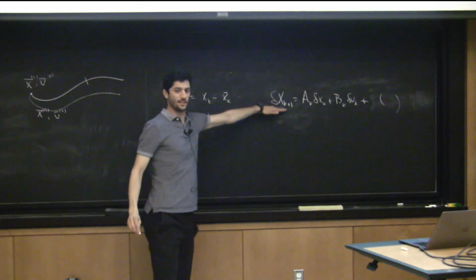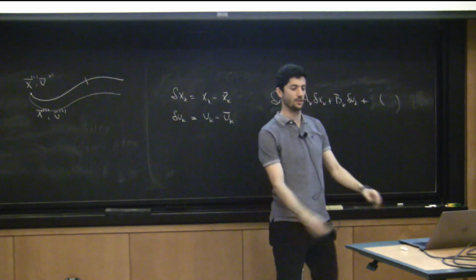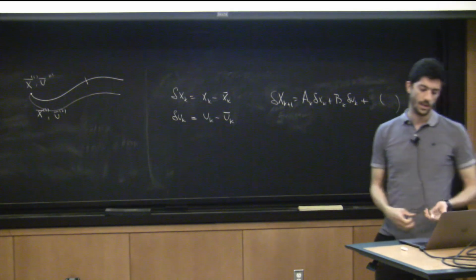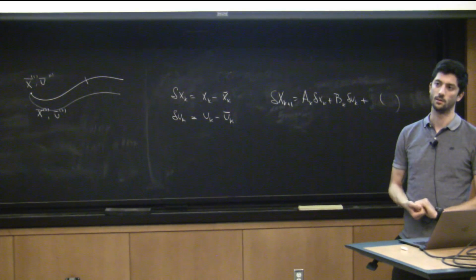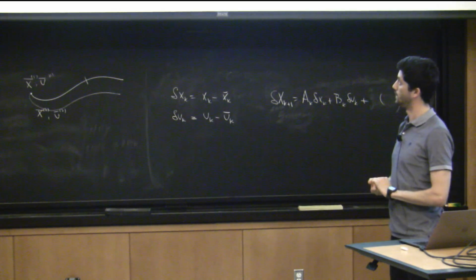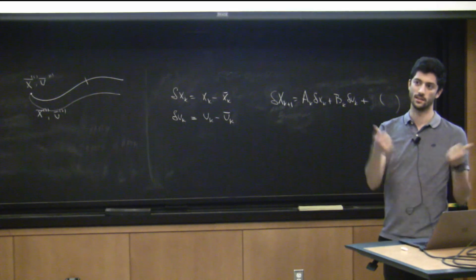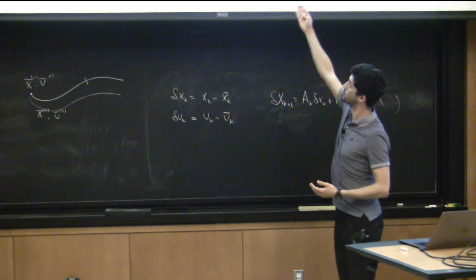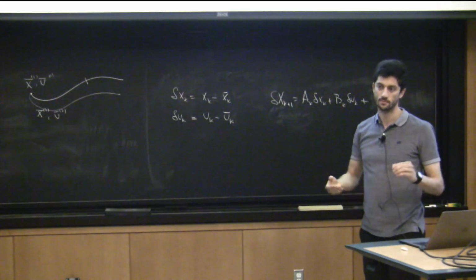So does everyone agree this is in the form of linear dynamics now? This extra term that you're seeing here has to do with the Gaussian noise, but I don't want you to worry too much about that. And we can do basically the same thing to expand the cost. So basically we can approximate the cost using terms that are either constants, linears, or quadratic in the delta x's and the delta u's. And this cost function and those dynamics fit into the LQR framework, basically.